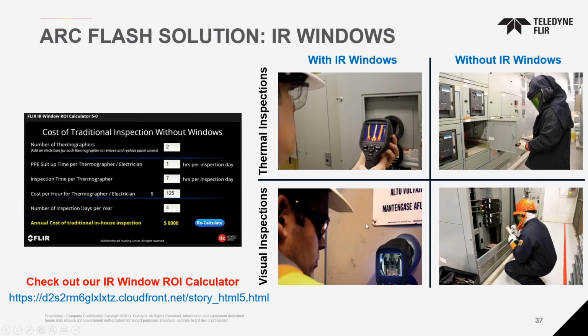The person on the left is wearing basically just safety glasses, a hat and a yellow vest. The person on the right has got a Cat 4 suit. He's fully suited up, gloves and everything else. So obviously, to set this up, do measurements and control cameras is a lot more time-consuming and harder versus someone just doing this. You open up the window, look inside the cabinet, and you see.